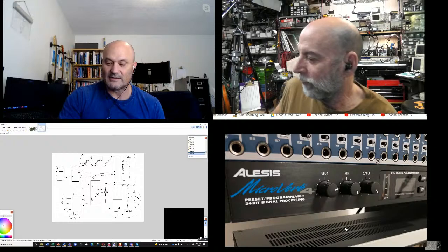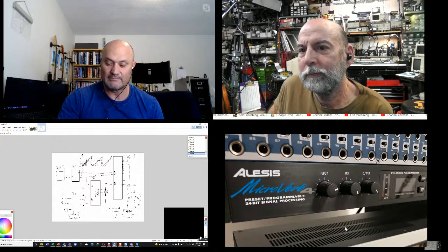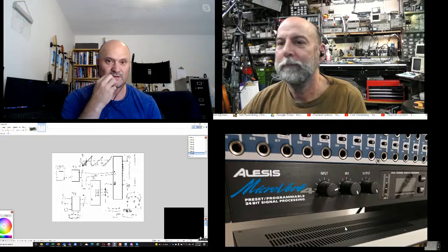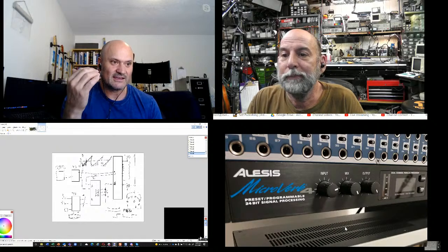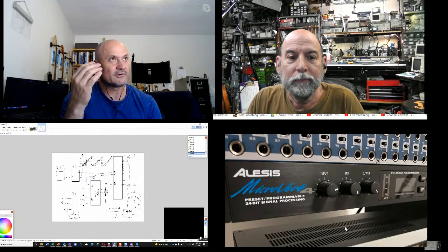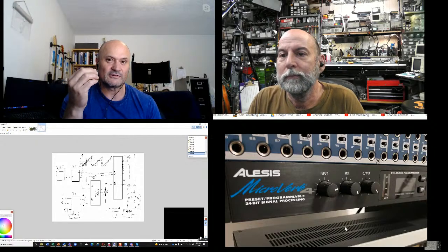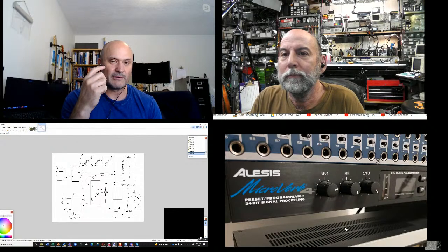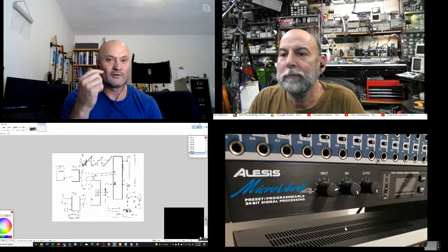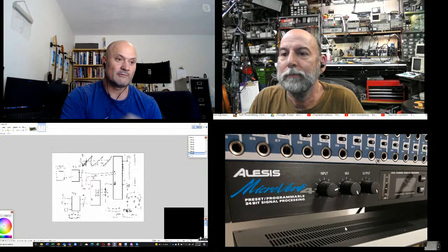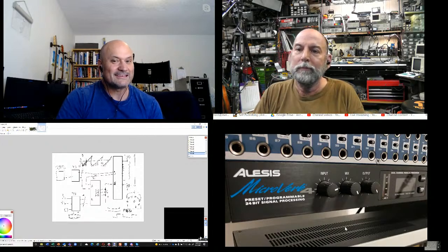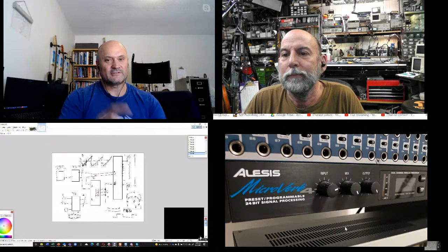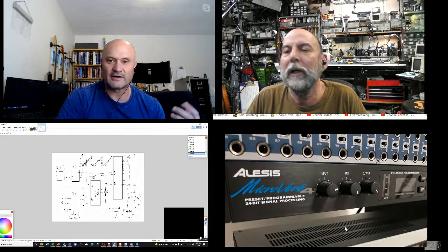Right, and sometimes guitar amp manufacturers deliberately bias the tubes hot because they say that's the tone people want. It adds that even harmonic, or is it even or odd? Anyway, I think it's odd harmonic distortion that's unique about a tube guitar amp. And so they'll deliberately bias the output tubes hot. But what it means is if you're playing regularly, like if you play once a week with that amp, you probably should be replacing your output tubes once a year. And that's pretty expensive because a set of matched output tubes is going to be $150.